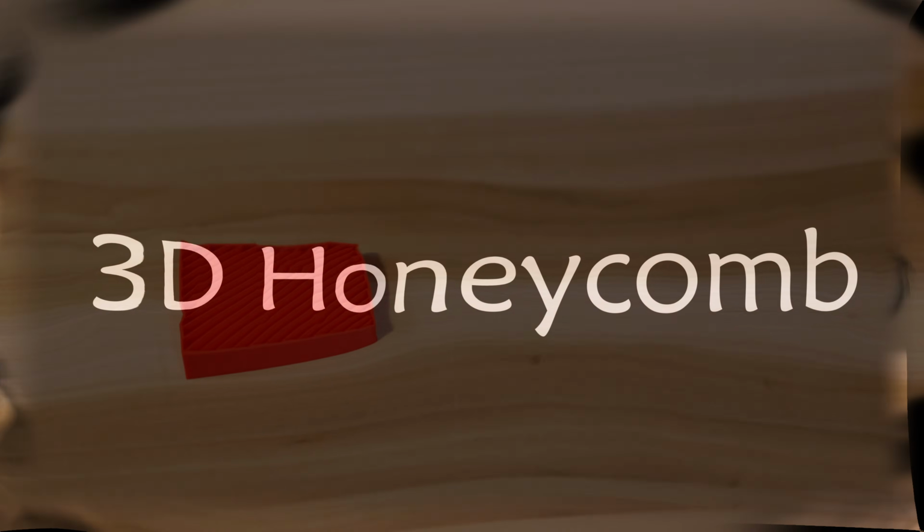The con is it is weaker interlayer adhesion, and a printing tip is ideal for non-load bearing parts. Okay, so quick to print, non-load bearing parts. For the cube that we're testing today, it took 1 hour, 5 minutes. It's 70.45 grams of material.